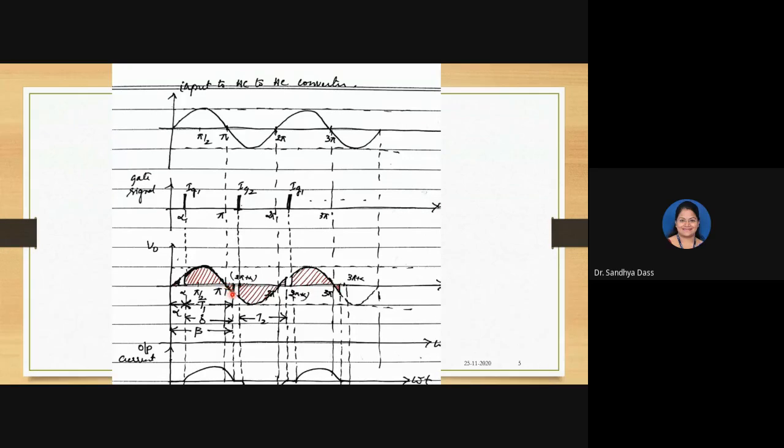Observe here clearly. This waveform is typically different from the previous ones, and you should be very attentive about this. Because the load is inductive, it causes the thyristor to continue to conduct even in the negative cycle for this much angle. Once the current from the inductor, that is the energy stored in the inductor, reaches 0, then T1 will turn off.